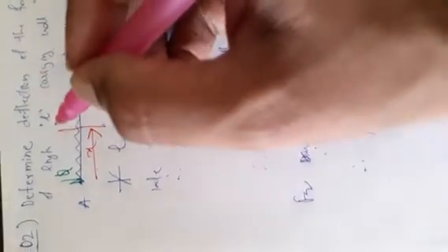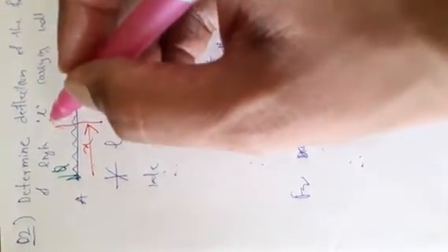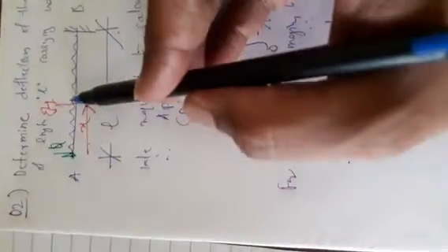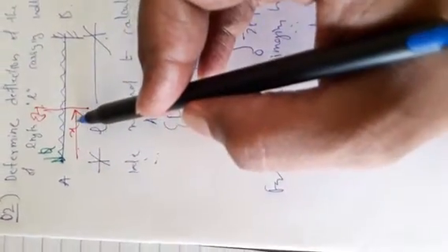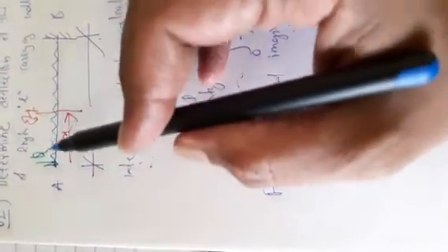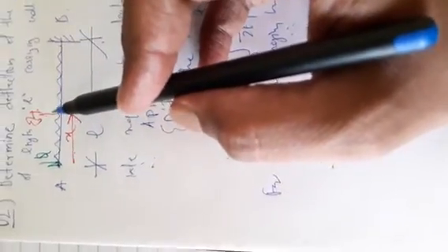Now let me find the equation for M. Moment at any section M. Just look here. Let this be any section at distance x. So moment at this section, again same sign convention, left hand side clockwise is positive, so these loads are anti-clockwise. So moment at this section because of Q is minus Q into x, then because of UDL W it is W into x by 2 into x.